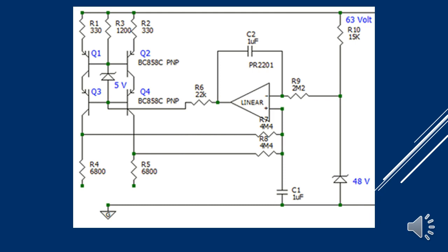And then he has what he wants, only now he doesn't see as much load as with the standard, because here is a current source. This is the first current transistor, and this is the second, to make it even better and to have a higher dynamic impedance. So this will be about 2 megaohm dynamic impedance instead of actually 0 ohm of the standard phantom.